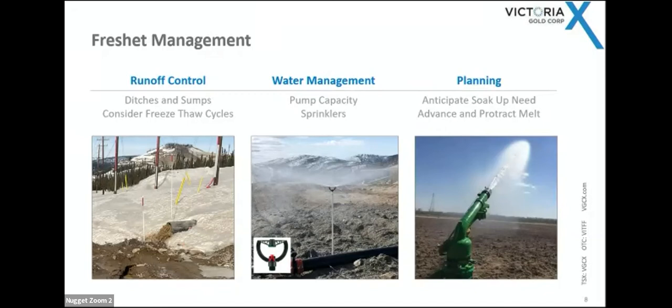And then the next thing is we're going to try this next year. In addition to that 180,000 cubes I mentioned that's coming at the site, we have about another 60 of melt infiltrating in the heap, and that also comes over a period of about 2 weeks. What we're going to try this year is get some of these big agricultural sprinklers, and starting in about mid-April, when the sun comes out and it starts getting warm in the days, we'll put these out and actually melt the snow, drive that melting, and pull all that water forward so that when the actual freshet comes, we can absorb the site water as well. So it's really just being able to manage that.